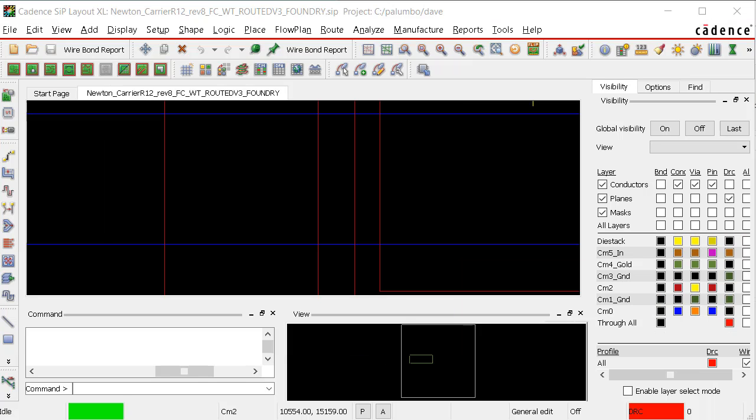So to start with, one of the most important things that we need to have are the required vias. And unlike in the classroom where I was creating via structures, we did not need to do that. We simply had a via definition that is going from CM0 to CM1, and a second definition that is going from CM1 to CM2. And by setting all of our constraints correctly, we can get the exact physical dimensions that we want for that structure.